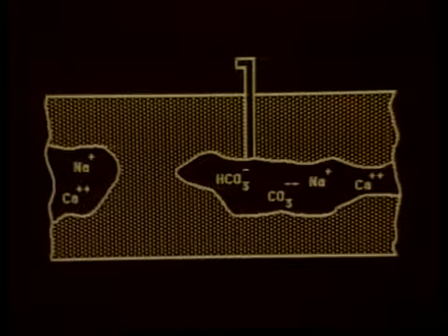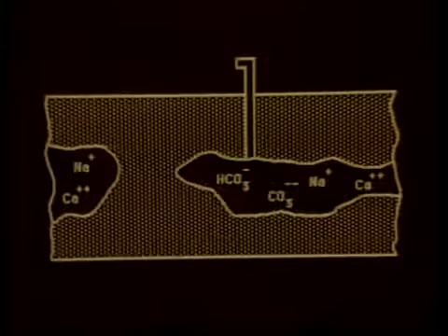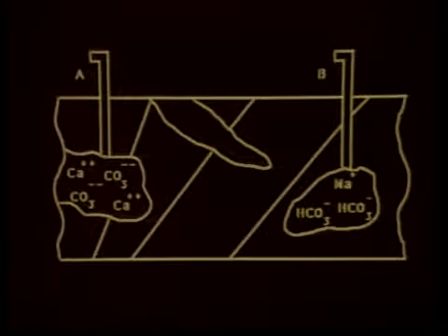The third type generally comes from strata which have very few available ions, mainly from strata deeper than sandy type aquifers, and few ions are present in these wells. By observing aquifer maps such as this, a producer may determine what type of groundwater source is located in his or her area. For example, a farmer at location A could drill a well and expect water from a limestone aquifer. On the other hand, any well drilled at location B would only produce water high in sodium and bicarbonate since the limestone aquifer is absent in this area.